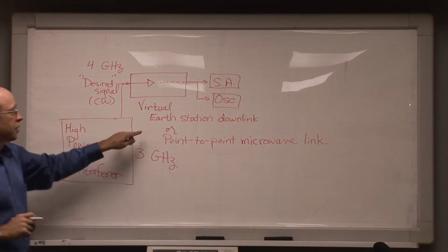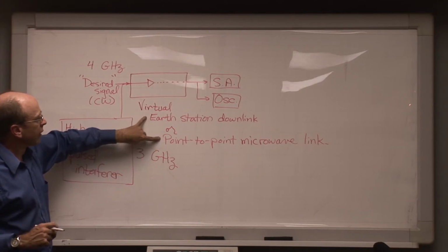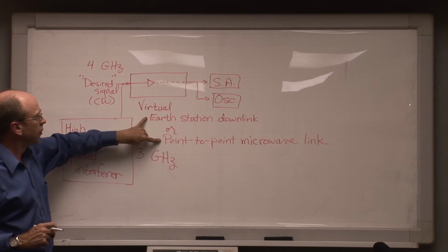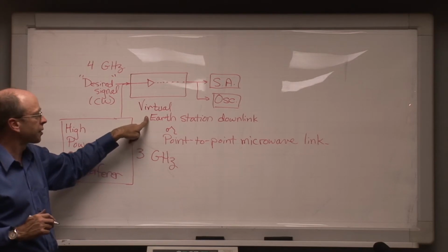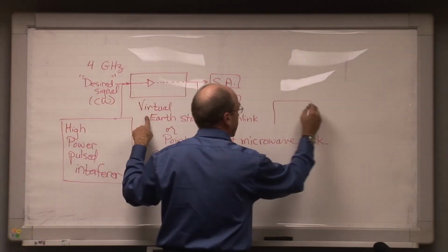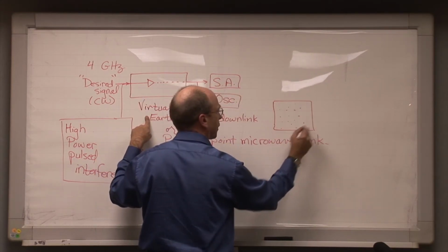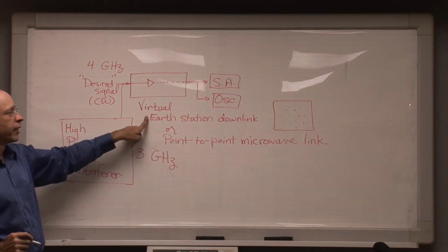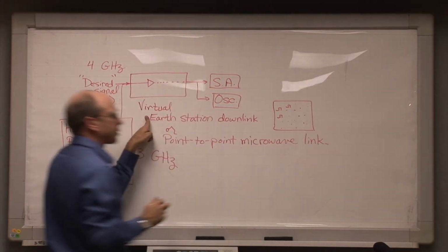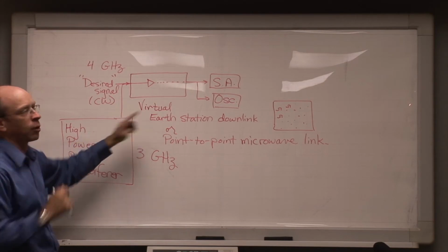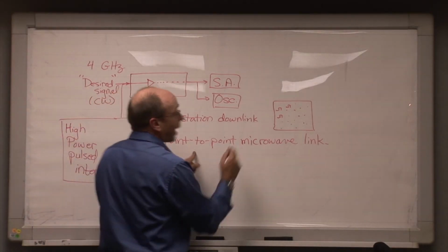One final note. Historically, when analog signals were being transmitted into earth stations and point-to-point microwave links, front-end overload occurred fairly frequently, but people tended to ignore it because with an earth station downlink that would be downlinking, for example, a television broadcast picture, people just saw a screen picture that showed the desired picture information along with a number of little speckles that would pop up on the screen whenever the interference would occur, each of these speckles representing one of the pulses that were coming from the pulsed interferer. And I've actually watched this myself in a hotel room, and I timed it, and it was 4.75 seconds, and I knew that it was interference from an FAA air traffic control radar. I was really bored that night.